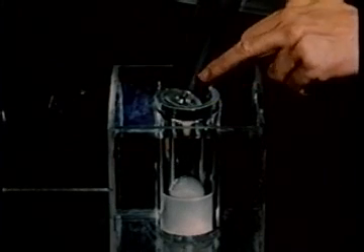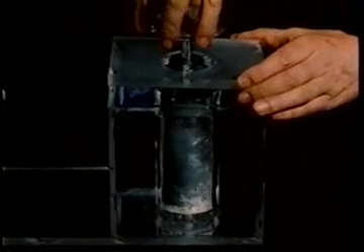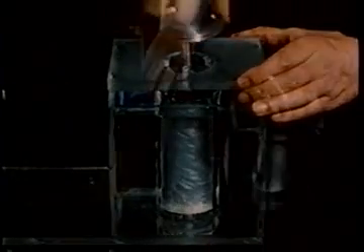For example, let us look at the flow between two concentric cylinders. The inner cylinder turns, the outer cylinder is stationary. We have put flakes in the fluid to make the flow visible. Turning the inner cylinder at an angular velocity less than a certain critical value, the flow is stable. Increasing the angular velocity to above critical, bands appear in the flow.